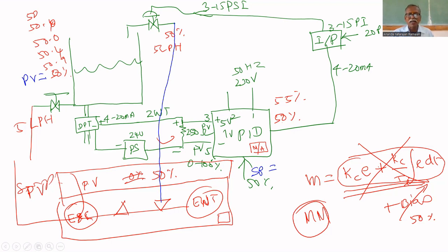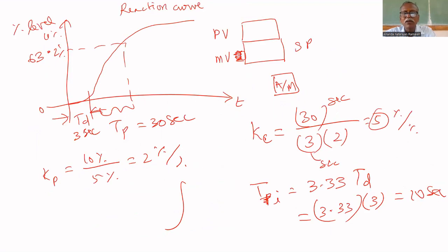How to enter controller parameters? For that, press escape one time, don't do auto manual transfer. Press escape when the display is set point. Here, there should not be O. If the display O is not there, it means it displays the set point. It must be 50. Why? Process variable is 50. Both are equal. At that time you press escape, it will enter inside the parameters.